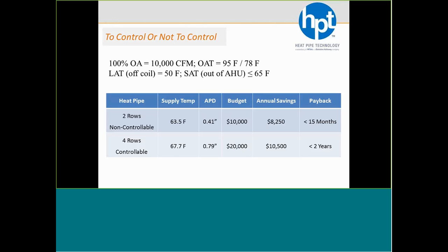When you add control valves, you're essentially adding friction to the heat pipe and the refrigerant circuit. Friction means energy loss, so that energy is going somewhere else. So instead of capturing all those BTUs, we lose a little bit of performance. Now instead of 20 degrees, we're getting almost 18 degrees of pre-cool and reheat. But we're still too hot on those peak days, so we're going to have to shut off some circuits on the very hot days. But the rest of the time, you are getting more BTUs than you would have if you had fewer rows.